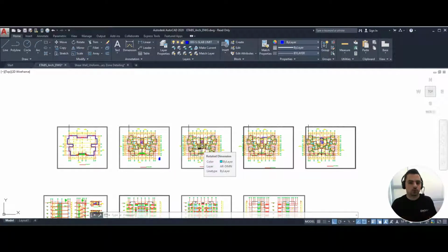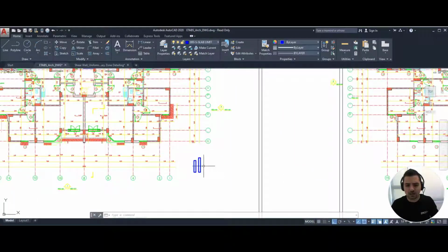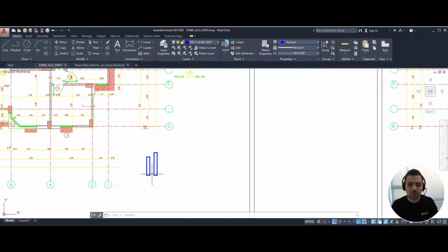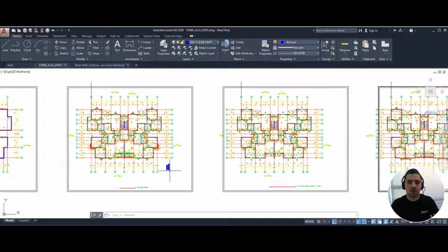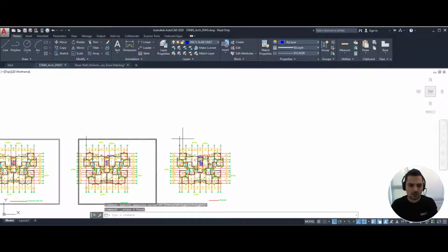Now what we usually do is every 3 to 4 floors, we try to increase the thickness of our shear wall by 5 centimeters. So let's take our case here. We have 8 floors. So the first 4 floors are going to have a dimension of 0.25 by, let's say, 1.85, and then your second 4 floors are going to have a dimension of 0.3 by 1.85. This is to make up for the increase in loading that is occurring at the lower floors. Now, one thing we can do here before we continue is delete these frames and our lines because we do not need them.